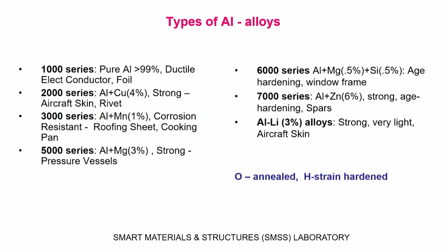But before I talk about that, I also want to tell you how complex the material selection process is. Just consider one material which I told you is very popular today: aluminum and its alloys. Aluminum and its alloys actually have 7 to 8 series, like let us say the 1000 series, one example, which is nothing but pure aluminum, 99% pure.